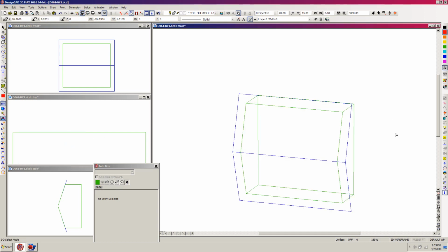So this is a pretty thin roof. It's just a plane, you know. So in order to extrude this roof out to the thickness it needs to be to look right for us, there's a couple of ways that we can approach this. Since we know what our trusses are, they're basically 2x4 trusses, and we have 5/8 inch roof sheathing on top of it. And I never draw the shingles; I just deal with the roof sheathing itself.